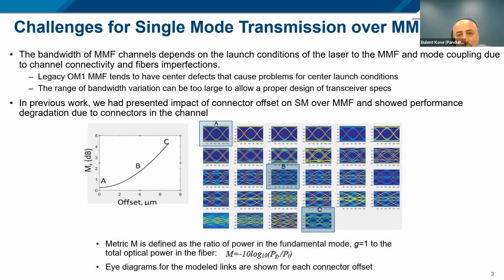But I would say it depends on the quality of that fiber. My F1 fiber is kind of our worst case gold standard, I would say. So if you have that fiber, maybe you're not going to be able to reach 6 kilometers. But if you use two of these modules at the beginning and end, you could go a couple of kilometers over 10 gigabit per second, and you can scale this, of course, for 40 gig, for 4 times 10, it'll be about the same. But if you go above 10 gigabit, you're going to have to scale the reach.